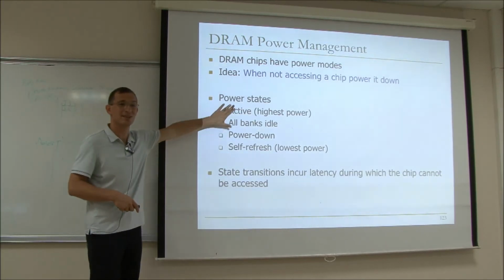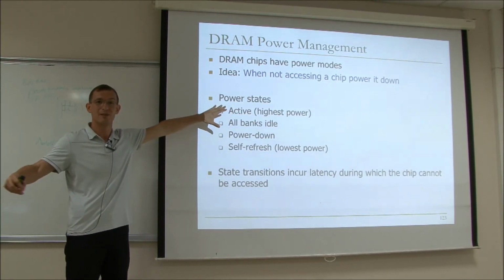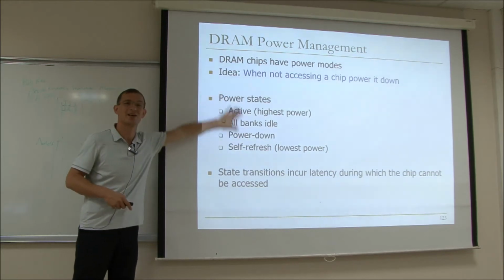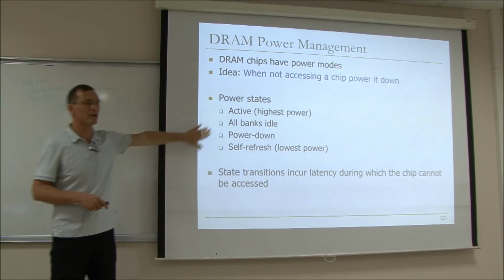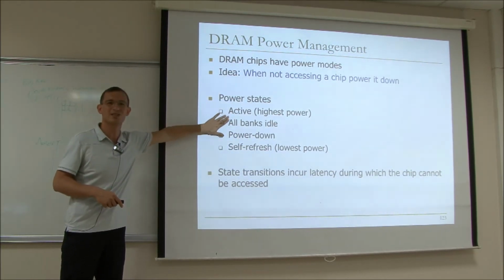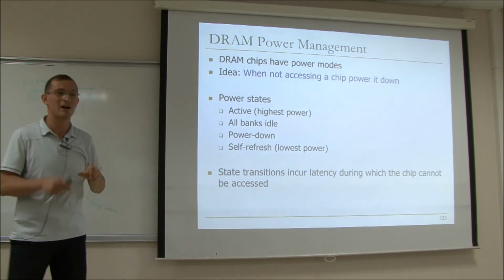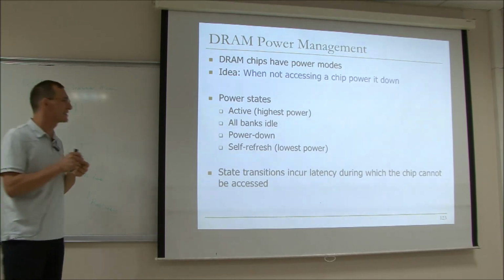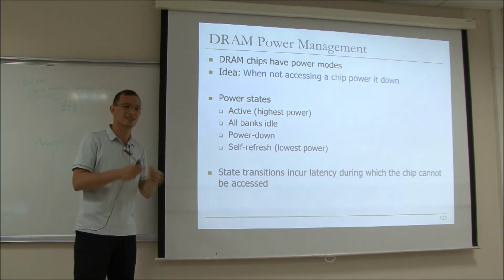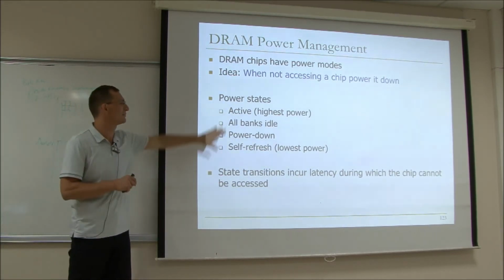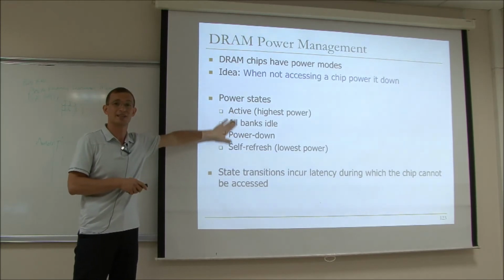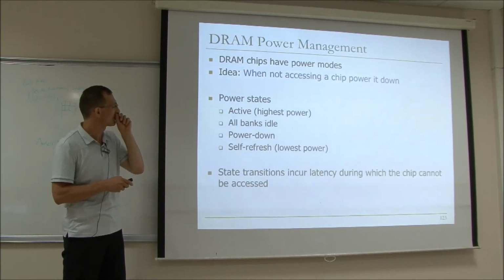If you're interested in this, I think going forward with multi-core, with memory interference, this becomes also interesting. How do you do the power management? And I think going forward, there will hopefully be more interesting and finer-grained power management in DRAM. If you look at today's DRAM, the power management is not at the bank level. It's actually at the rank level, which is very coarse grain. If you can do it at the bank level, you can probably get better power characteristics.